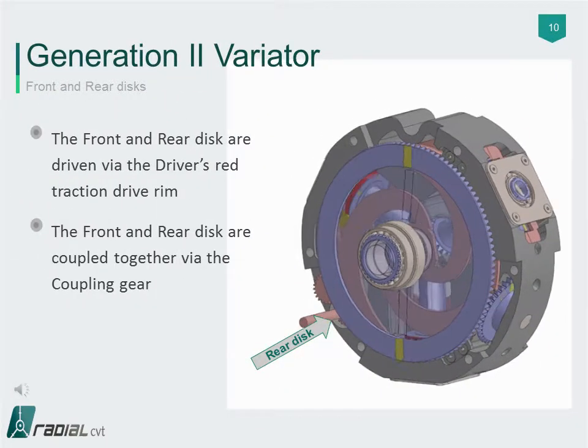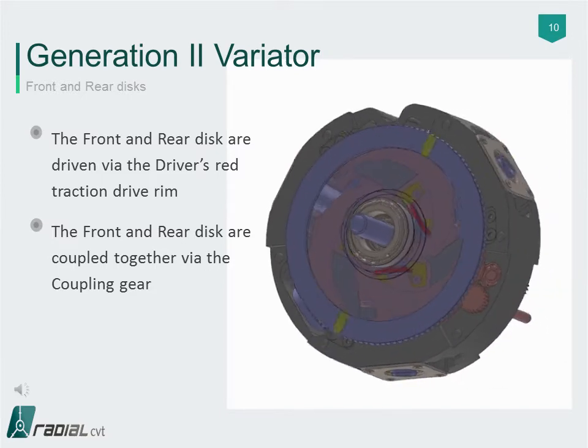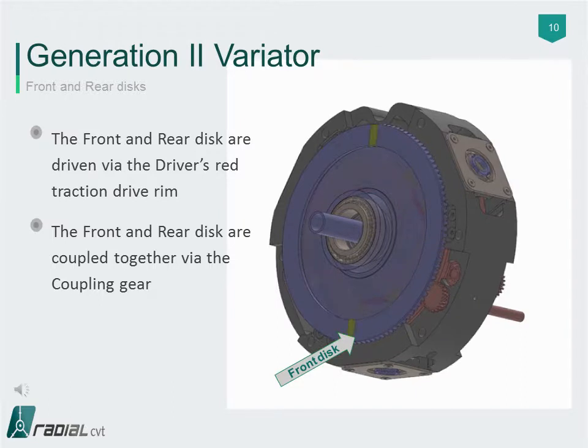The current Gen 2 radial CVT design includes two ratio spirals, one on each side, in order to provide a balanced shifting force on the adjusters. Prototype tests might prove that only one is needed, and simplify the design even more. The Gen 2 radial CVT in this configuration is ideal for EVs. The Gen 1 first prototype tests already produced transmission efficiencies between 85 to 90% through its ratio range, and the Gen 2 is expected to significantly improve on this.